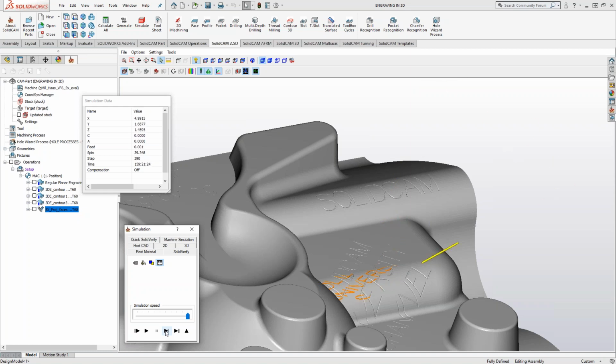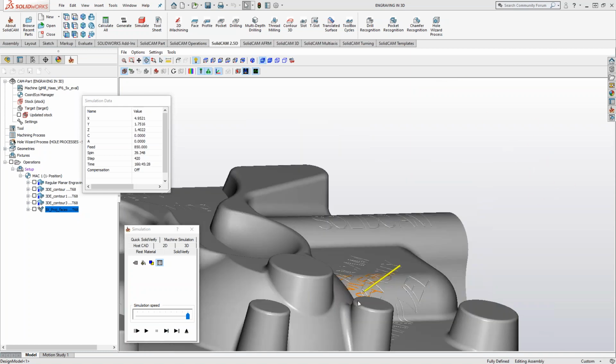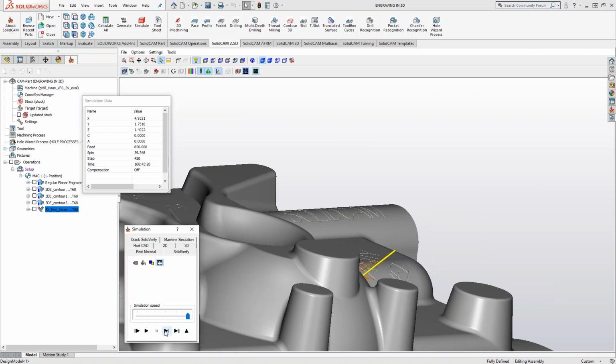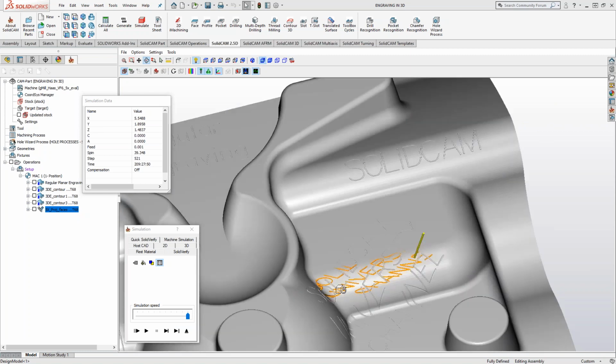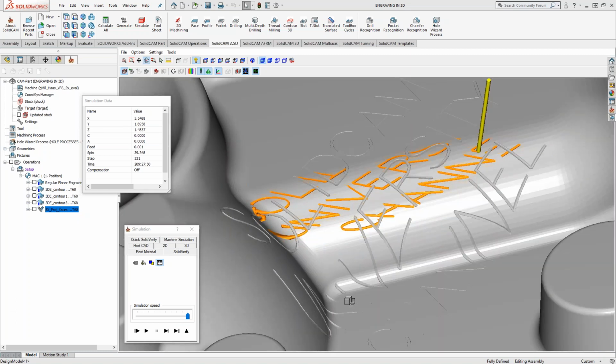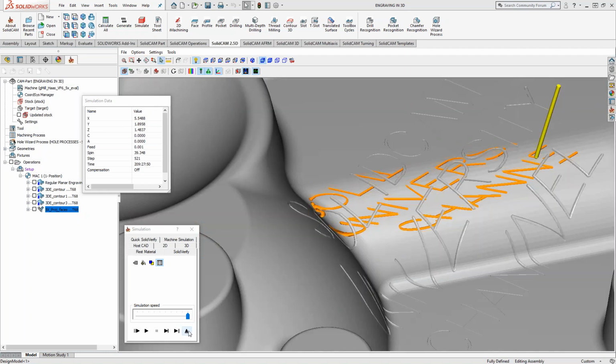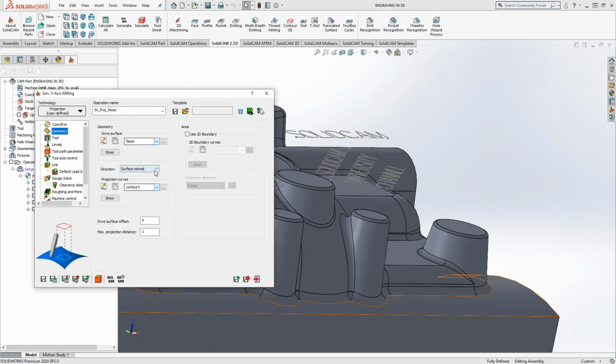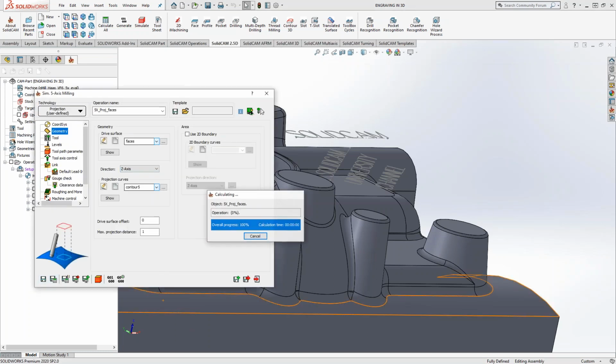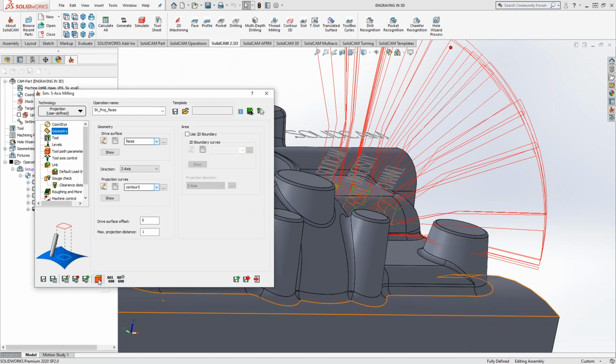Now with 5-axis, with those tilt angles and all that stuff, the sky's the limit on what you guys can do in there, because we can kick that tool over all the way to 90 degrees, depending on what you guys are using for holder. Use your gouge protection to make sure we're not hitting the holder against the workpiece or shanking out against the workpiece. All that as well.